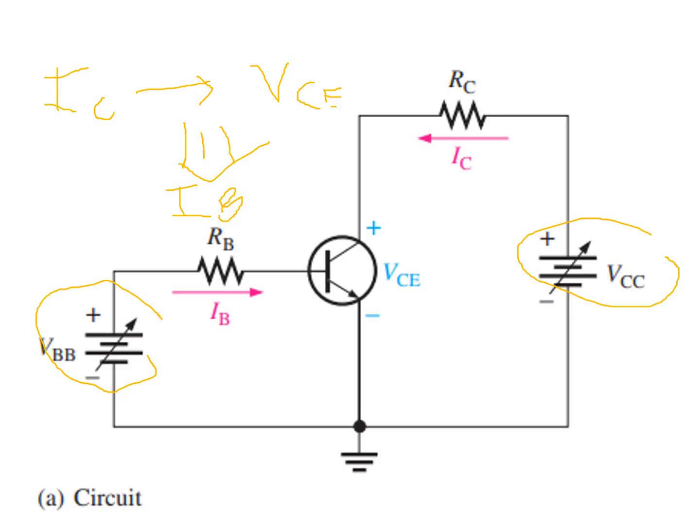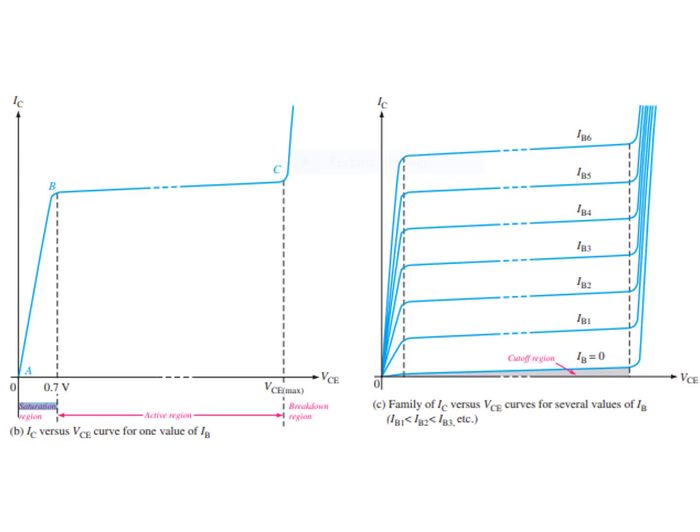For this condition, both the base-emitter and base-collector junctions are forward biased, because the base is approximately 0.7 V while the emitter and the collector are at 0 V. The base current goes through the base-emitter junction because of the low impedance path to ground, and therefore IC is 0.